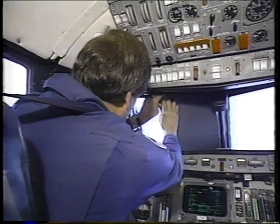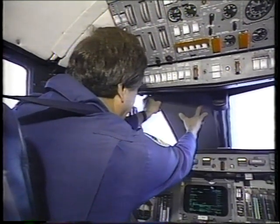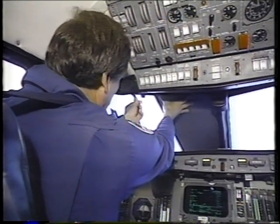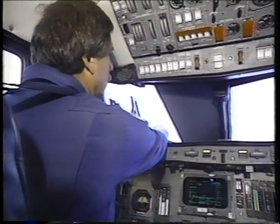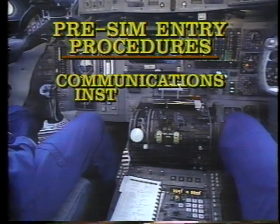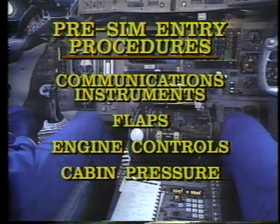During the flight to the training area, the crew performs pre-sim entry procedures. Masks are inserted into the cockpit windows to simulate the view from the shuttle cockpit. Communications instruments, flaps, engine controls, and cabin pressure are adjusted to the proper configuration. The pre-sim procedures should be completed by the time the STA reaches its desired altitude.